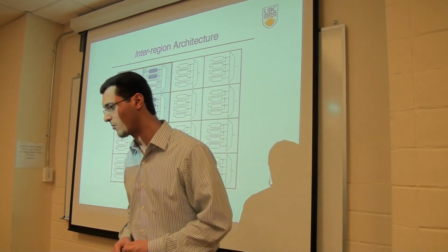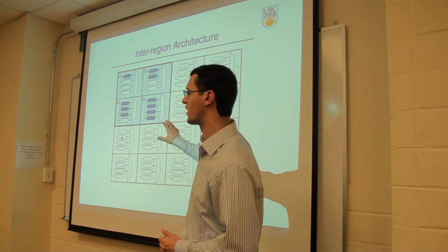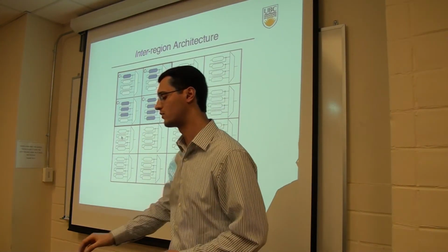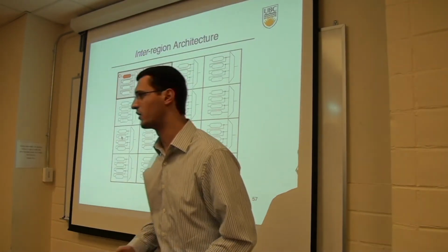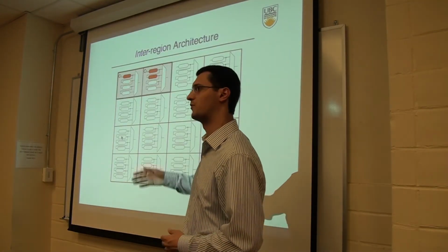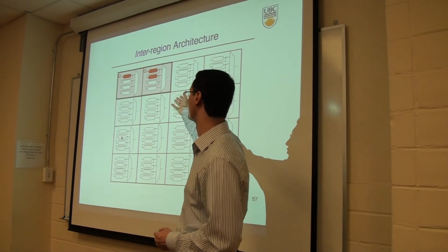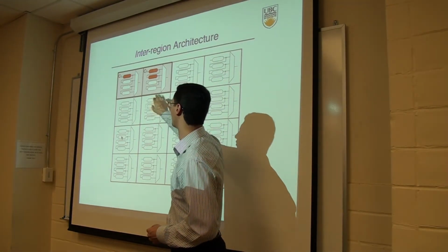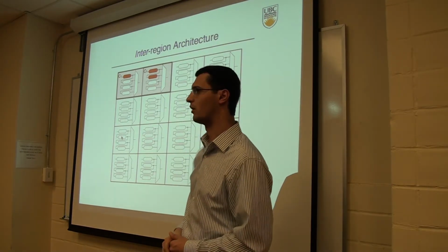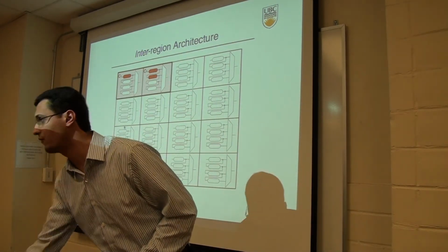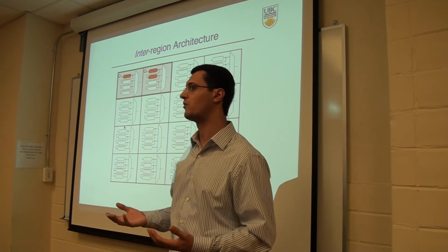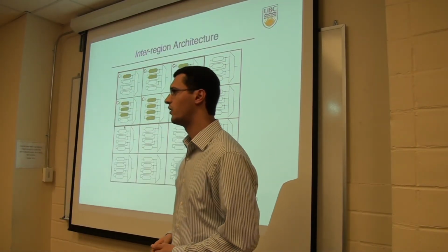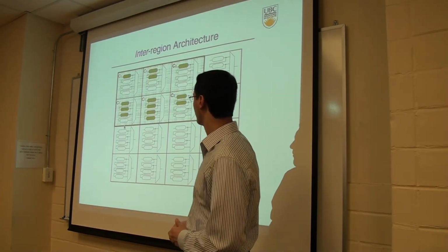Okay. So this is if the application size is similar to the size of the programmable delay element. So what if the application size is smaller? It's straightforward. We can just use two delays to sequence the wake up of the application. What if the application size is larger than what the programmable delay element could provide? So basically we leave that to the designer.